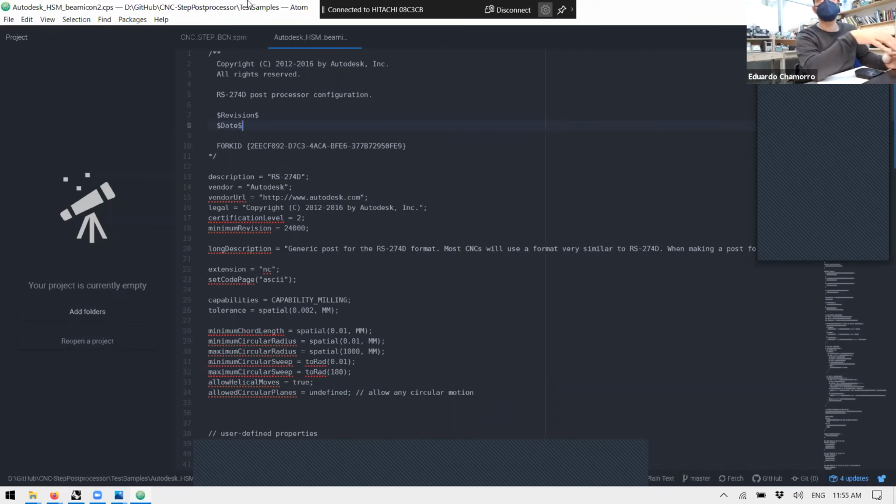So in general, we go back into RhinoCam, change a few settings, like curve interpolation, and that line disappears. If you launch a file and the program highlights one line in red, just tell us. It might be that the post processor is not working exactly as it should.